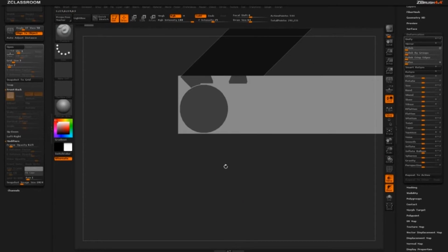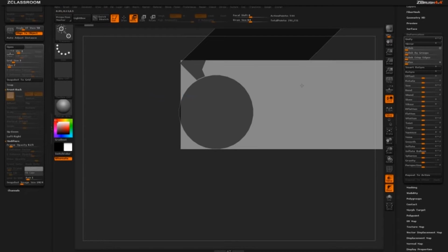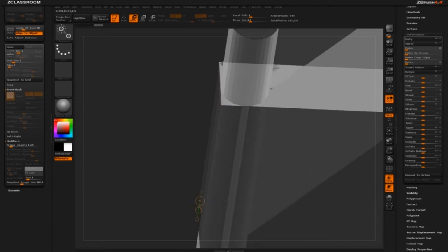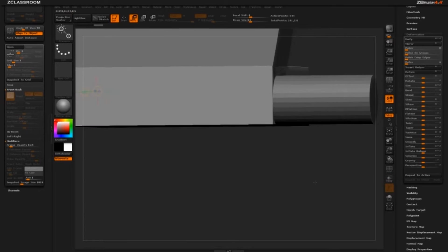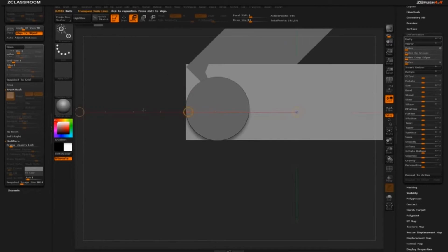Now this box, I want to get it lined up so it's directly hitting the curves here. So I'm just going to use the move option again, holding Alt, and position the box so both those parts literally just touch the bottoms of the cylinders, because I want this shape to be a clean cut, or as clean as it can be. So something like that. I'll move this a little bit more, so we have a little bit of it hanging out.